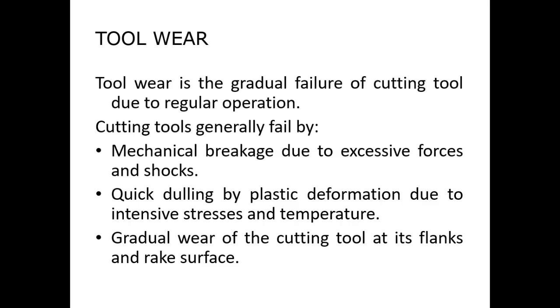This is one such common phenomenon where, with usage of a cutting tool for a certain period of time, wear will occur due to friction. The friction that exists between the cutting tool and a workpiece causes this wear. We can reduce this type of tool wear by taking utmost care during the machining process, by providing cutting fluid or a lubricant, or by machining at the lowest speed, feed and depth of cut.